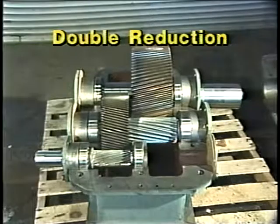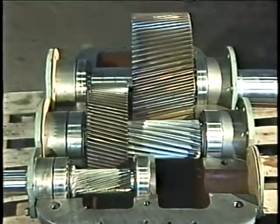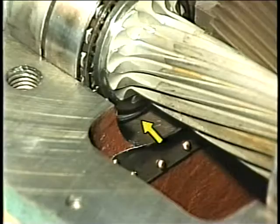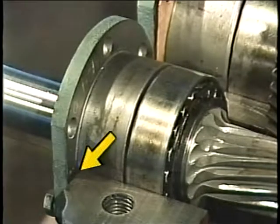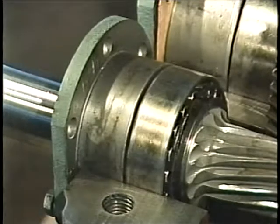This gearbox is a double reduction type. It steps down the motor speed in 2 stages. The first stage of speed reduction occurs across this helical pinion and gear. The second stage of reduction occurs across this pinion and gear. The pinions and gears are mounted on shafts, which are supported by bearings on either end. The bearings are supported in parts of the casing referred to as the bearing housings. Spacers or shims are placed between the bearing housings and the end caps to properly position the bearings, shafts, and gears inside the casing halves.